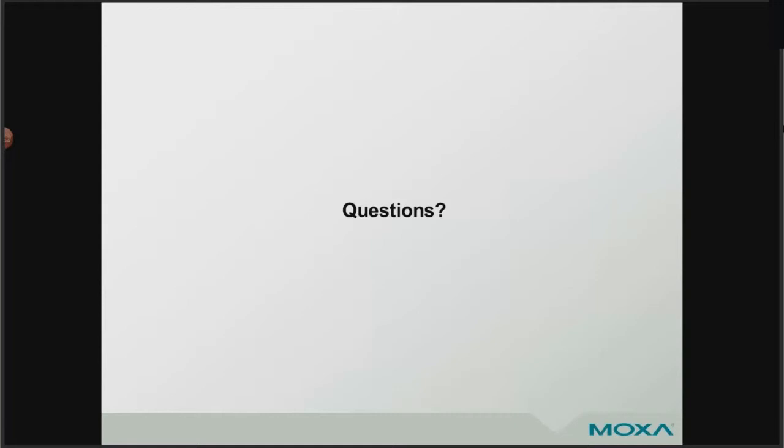And then the follow-up to that question was, what is the best firewall for Moxa for securing a controls network from a corporate network? Well, that really depends on where you're using it and what you're trying to protect from. I think Ariana talked a little bit about the tiered approach, where you typically will have a firewall that's isolating the manufacturing portion of the network from your enterprise network, and typically there'll be some sort of DMZ or demilitarized zone in between.